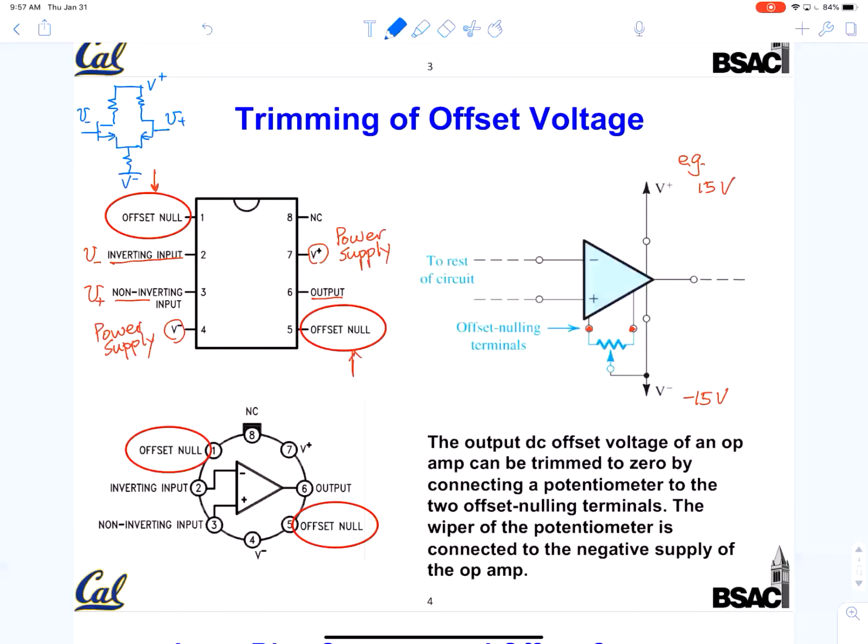And if these two resistors are identical, and these two transistors are identical, then you expect the output voltage, which we take out from here, to be exactly 0. But imagine one of the resistors is off by 1%. That leads to unbalanced operation, and as a result, the output is not exactly 0 when it should be 0. And we will look at this circuit towards the end of the semester.